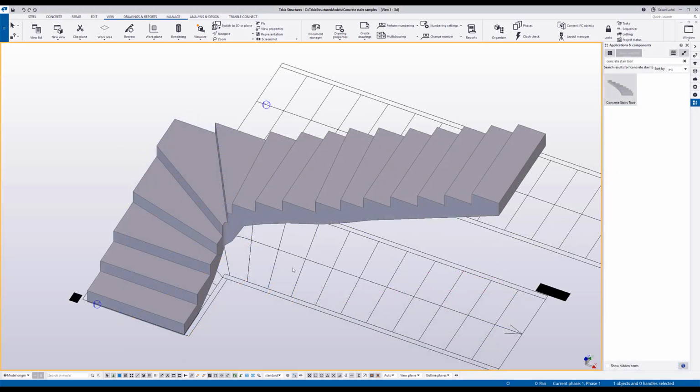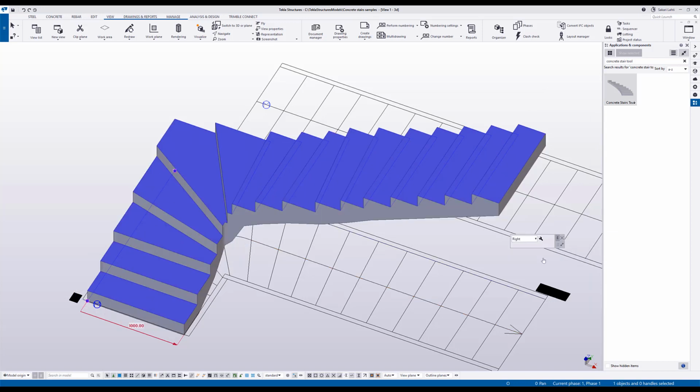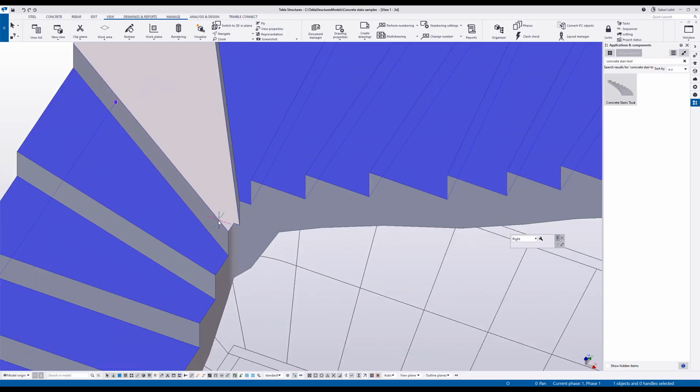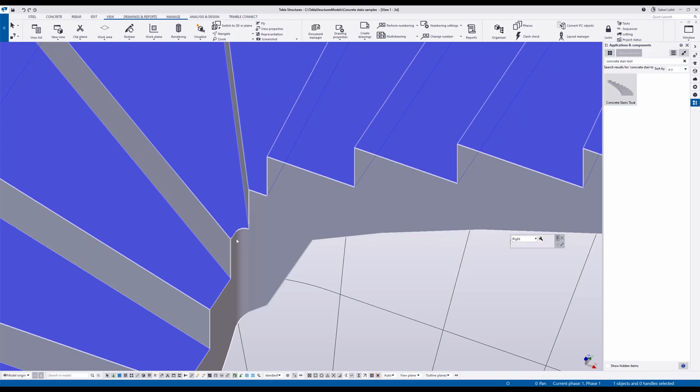You can also convert the stairs that you created with the first 4 options to be advanced stair. In the contextual toolbar, you have a button Convert to Advanced Stairs. And after you convert it, you are not able to use the same direct modification features as you would have for typical L stair in this case. But it will give you freedom of editing these individual steps, for example, adding a rounding to this corner point. So making it round and also making round corner chamfer of 40 millimeters as an example.